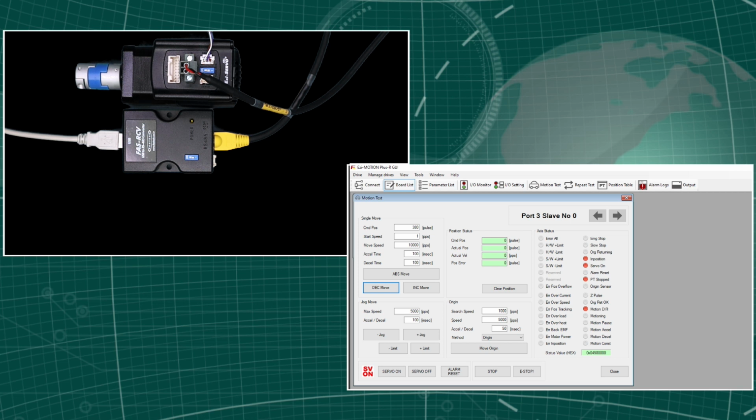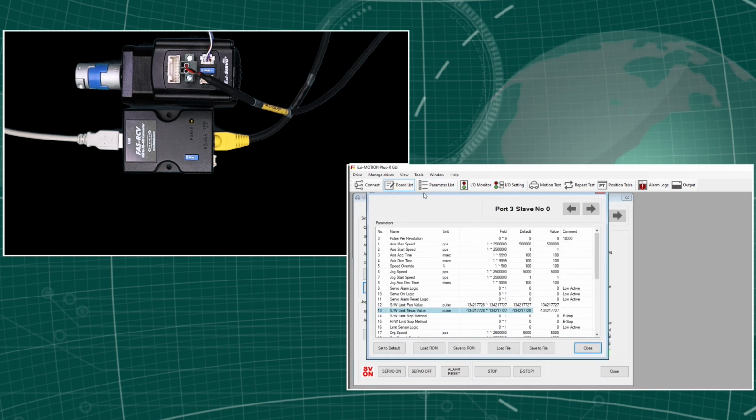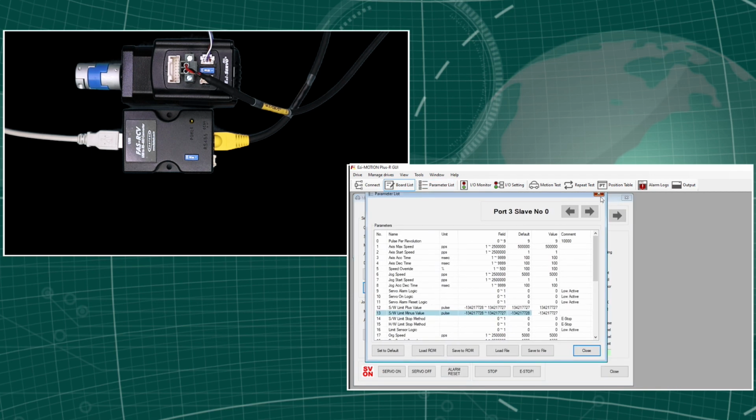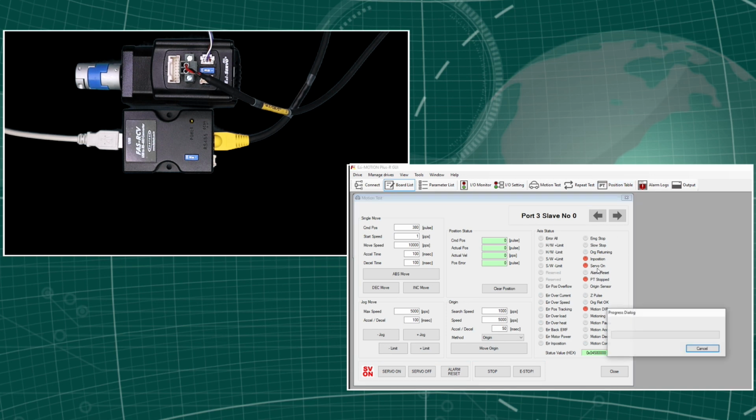If you want to program different situations or different positions, you can do this with standard programming software like C# or LabVIEW. You will get a complete command list together with the motor software, so that you can easily program your positions. If you do not want to program in another system, you can also use our parameter list, our position table.